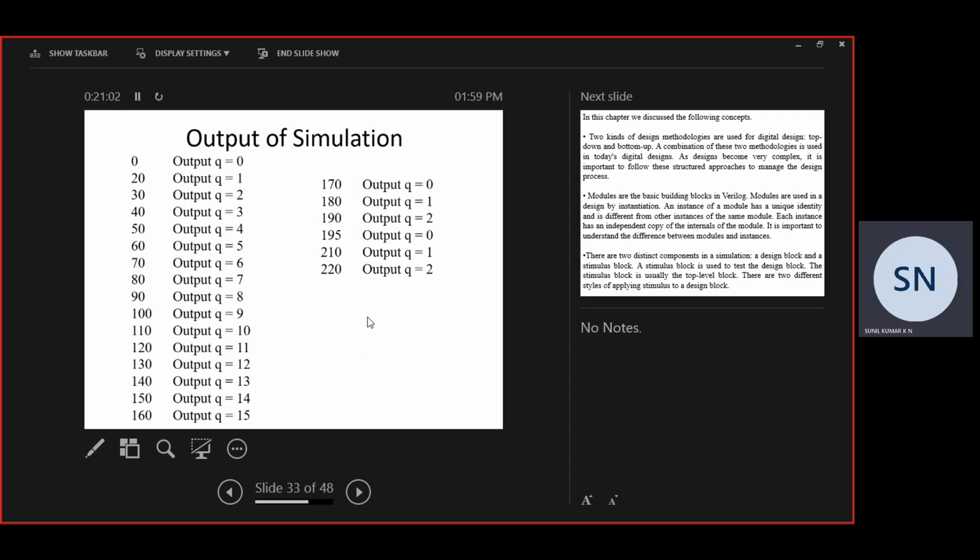It is a four bit ripple carry adder, 4 bits. A is of 4 bits, B is of 4 bits, sum is of 4 bits, C out is 1 bit, C in is 1 bit. A [3:0], B [3:0]. How can I divide this ripple carry adder?